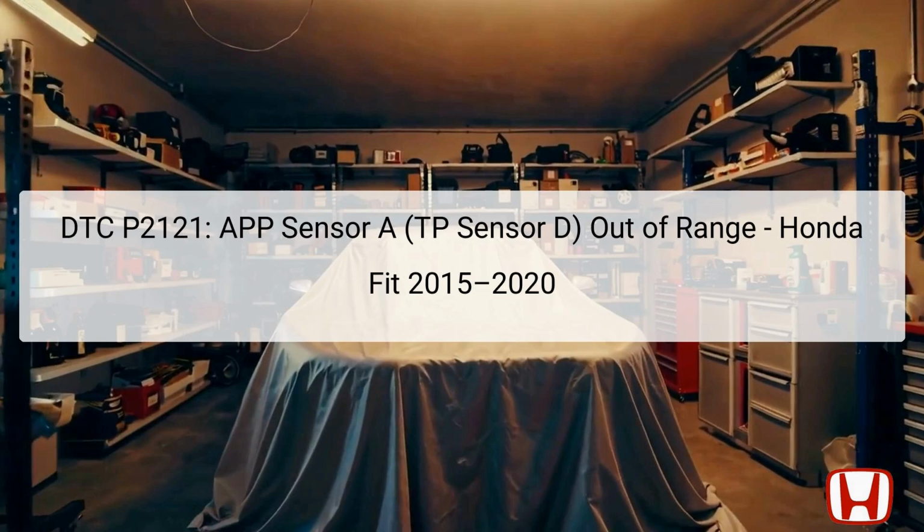The diagnostic trouble code DTC P2121 indicates that the accelerator pedal position APP sensor A, also termed as TP sensor D, is reporting an out-of-range condition. This signal is critical as it communicates the position of the accelerator pedal to the powertrain control module PCM. The PCM utilizes this information to adjust fuel delivery, engine performance, and compliance with emission standards.